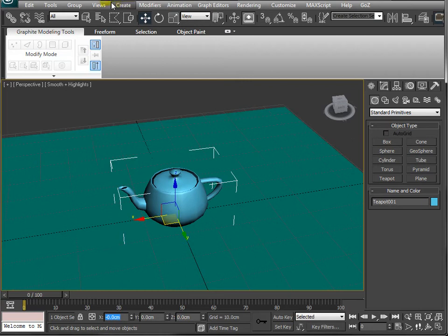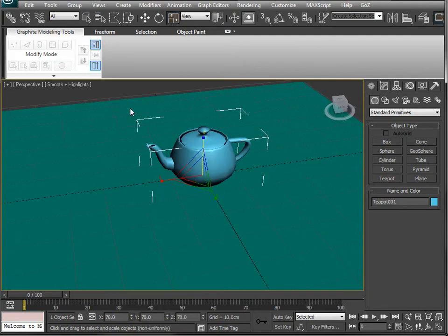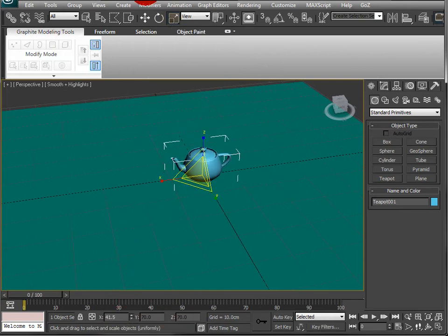Or you might want to change the scale. There we go. So at the moment it's got a scale of 68.669. I want that to be exactly 70, so it gives you real precision to work with there. Pressing R again. So now we're in the non-uniform scale, and it's opened up all the options here. So before, when it's in uniform scale, I can only change one, and it changes them all together, which is different to in this window, where I can change them individually. But if I'm in non-uniform scale, I can numerically change all of them together. So it's a useful little thing to know.